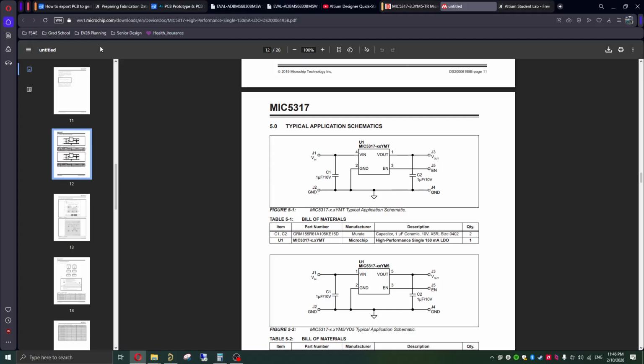And also one last thing that I wanted to mention that is going to be important is to choose your fabrication house. On Courseworks, there is a recommendation to use, I think it's Advanced PCBs, because it's a domestic supplier. You can, as far as I know, use different fab houses. Ones from China are typically cheaper, but they sometimes have longer lead times. I've been most comfortable using the JLC PCB fab house capabilities.